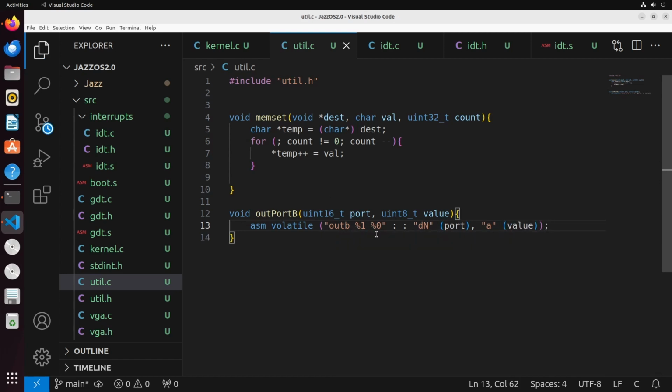So you may not have ever seen this operation before. I never really talked about it in the x86 video so far. What it does is it outputs a byte of data to a specified IO port. All of these different ports on your CPU could be hooked up to different chips. So one of them is hooked up to those PICs, and we're going to write data to the port that's hooked up to those PICs. So we can send data directly to those chips. That's the idea of what we're doing with this port value setup.